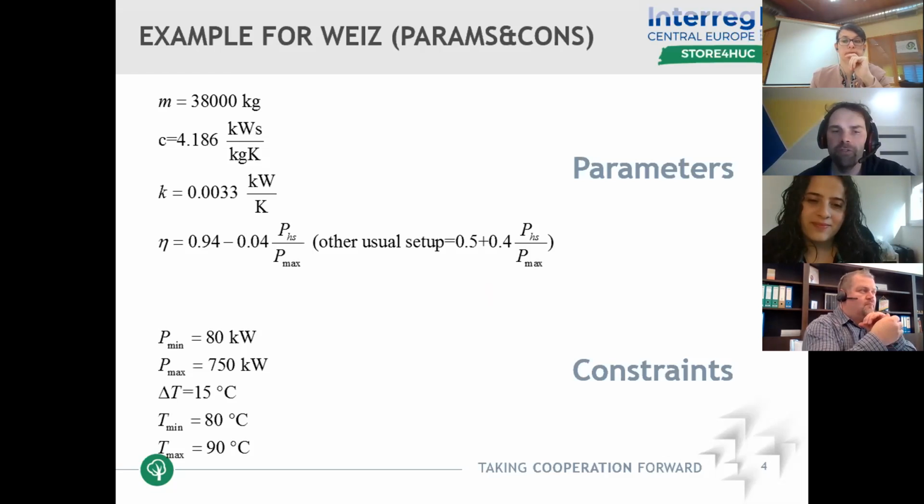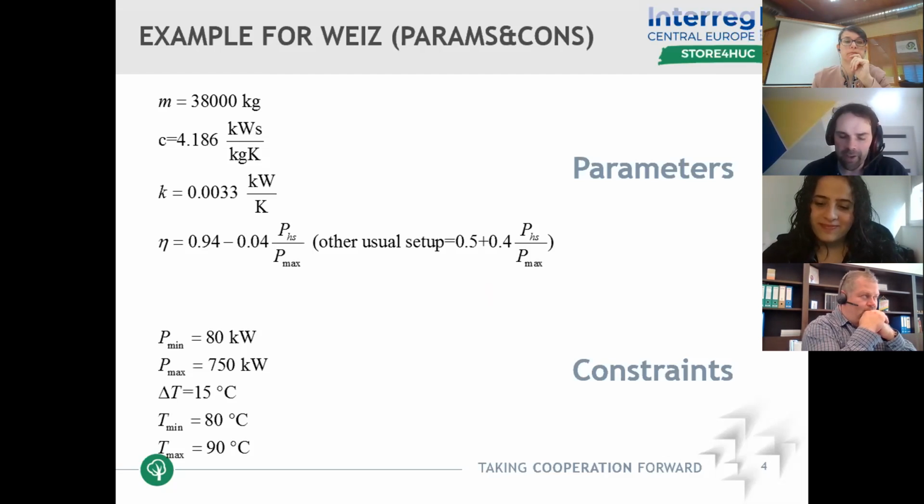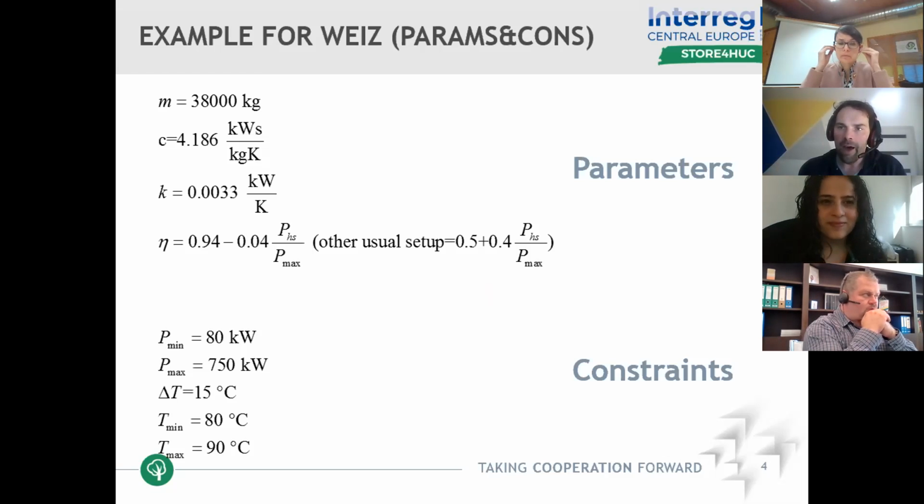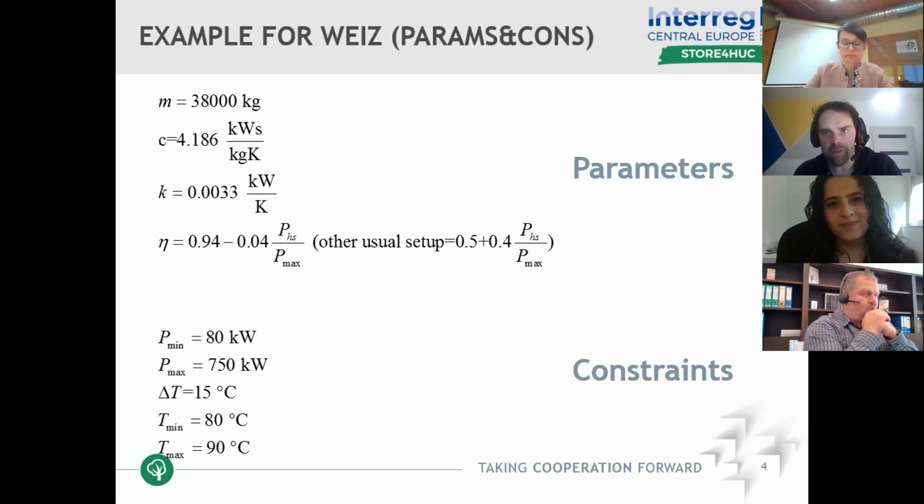If you would have online execution of this code, I was mentioning it. It's a possibility with a very advanced system where you have a server available locally that is connected to your SCADA system, and then this server computes exactly these power profiles and engages the system with these profiles. So the beginning of the profile, it directly commands to the system, and the rest is its plan. And this plan is always repeated, for instance, each 15 minutes.